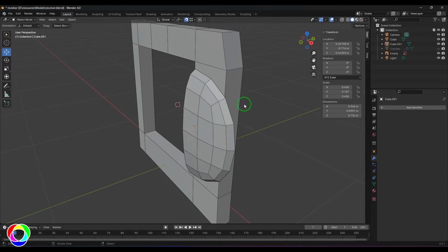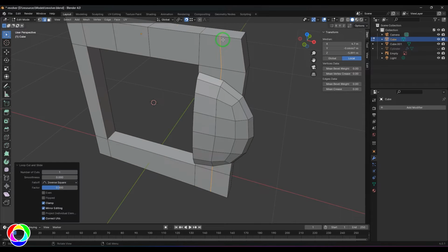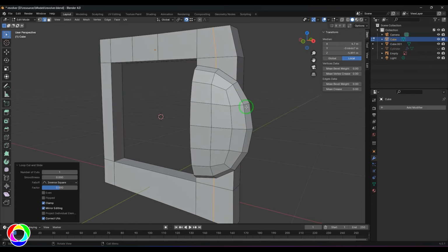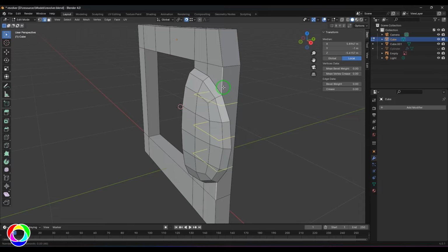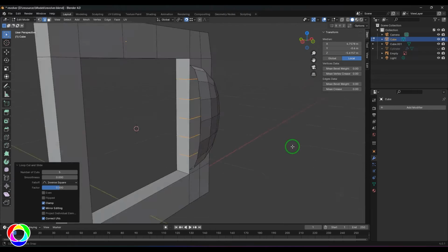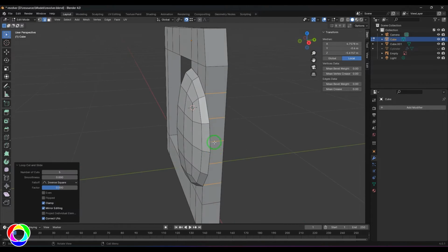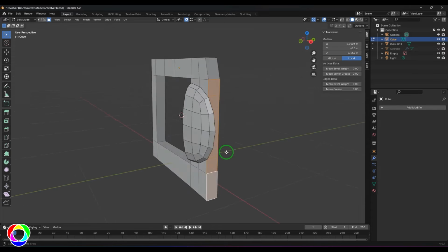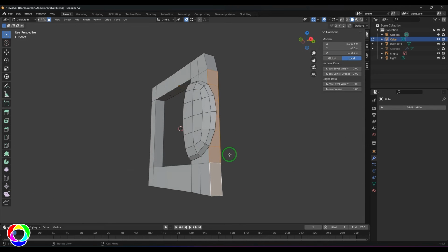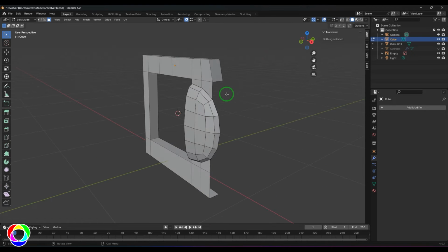And I need some lines. Maybe I'm going to select this model, press Ctrl R, and that adds a line. Ctrl R, and then I'm going to add a set of lines there, so that the lines are going to connect with the surface properly. Okay, so let me select those faces. So maybe I can delete those faces for time being,